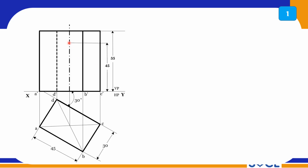So here this is 45 mm on the axis, on the axis the cutting plane passes through this point, right? So 45 mm from base, and this cutting plane is inclined at 30 degrees to HP, and this is the cutting plane representation. Through the solid draw the thick line, and then the axis line. At the ends you draw thick lines and show the arrowhead like this, and this is my first cutting point. So the first cutting point I am obtaining on the A vertical edge, and the second cutting point I am just notating in order, in this order only. So on the B edge I am going to obtain point number 2.